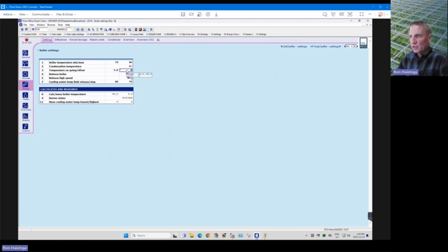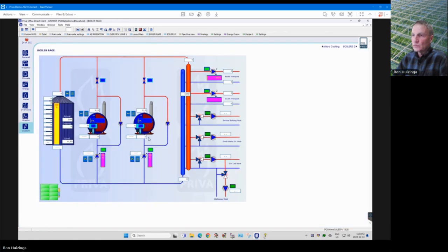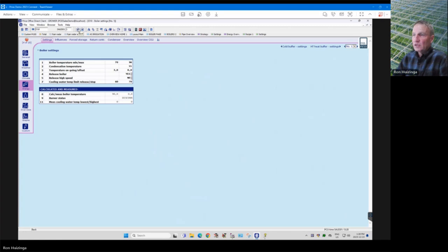But if you have a buffer system, then I call this pump here the fill circuit, because that pump pumps the water through the boiler into the tank and fills the tank up with water. So we call this a fill circuit. Then that fill circuit is going to adjust and try to target 90 degrees all the time to fill the buffer tank.